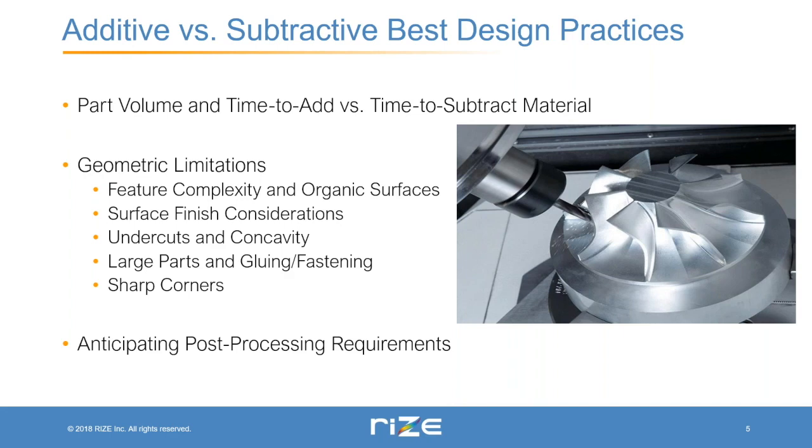So if a part has been designed to have corners that were developed for subtractive manufacturing, and that part is intended to be prepared for additive manufacturing, it can be good to go through and look at those corners and make sure that all of the convex ones and concave ones are prepared properly for the process you're using.